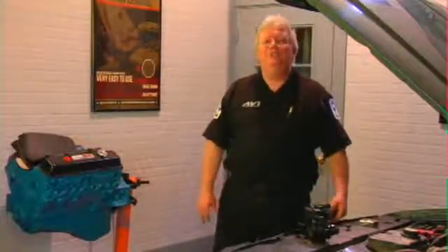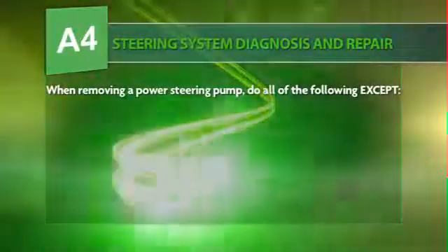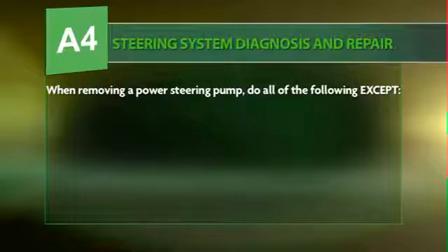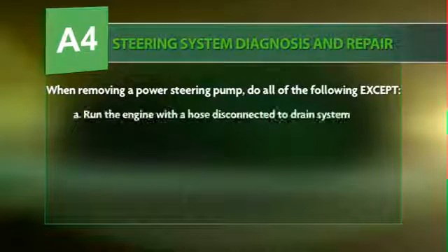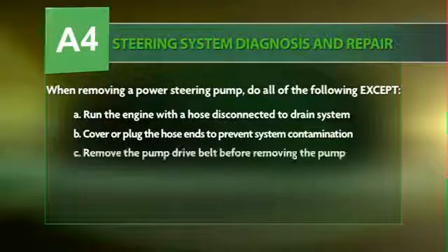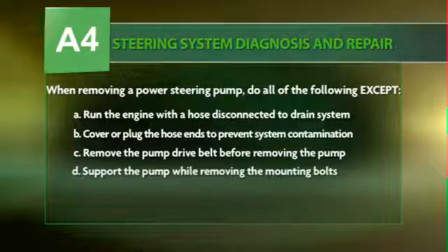Let's go on to our next question. This has to do with the power steering pump as well. It says, when removing the power steering pump, do all the following except, so we're looking for the wrong answer once again. A, run the engine with a hose disconnected to drain the system. B, cover or plug the hose ends to prevent system contamination. C, remove the pump drive belt before removing the pump. Or D, support the pump while removing the mounts. Okay, so now we're looking for a wrong answer here.